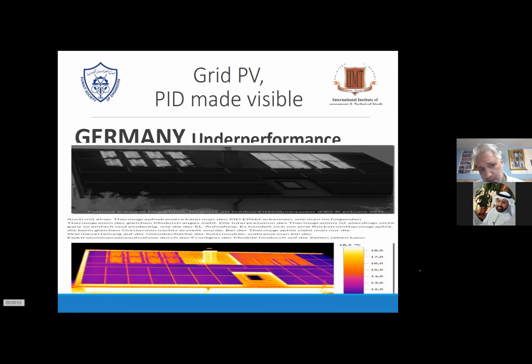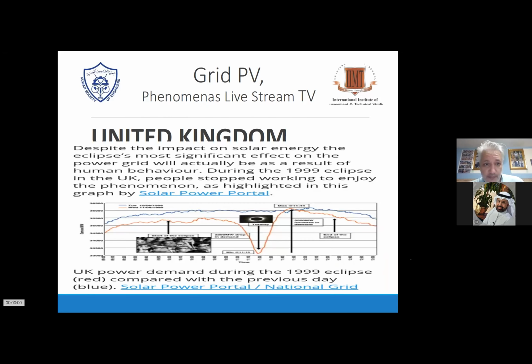So the dark wafers, they're already affected by PID. So the one side is mostly the negative. That means the top section, most of the time, is affecting one side of the strings. So the plus always looks better than the minus. This is another sample where systems have problems and don't have problems.